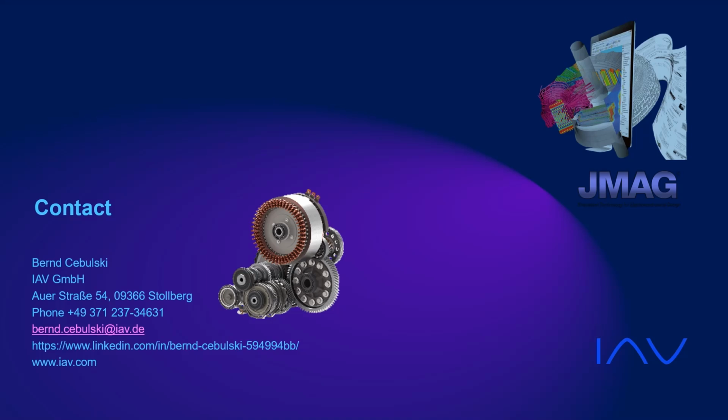Yeah. And the question is, you mentioned RT, but we also need to care about the demagnetization dynamically. So we need to support dynamic demagnetization in RT, or we need to think about an FEA direct link with the control. For RT, this would really be nice to have, because then, as Takashi asked, we can shift the problem to our control designers. If we could deliver an RT model, then the control engineer can take care of a lot of failures, which is not the case right now. Now we just support static characteristics, so we need to think about the dynamic behavior of the machines. Yes. Okay. Thank you. You're welcome.